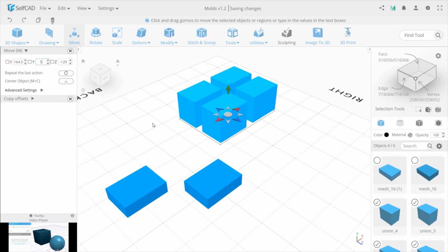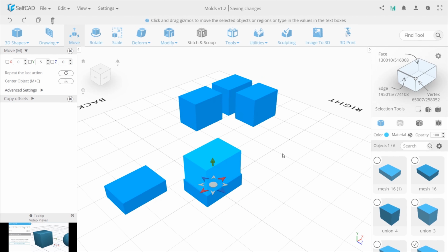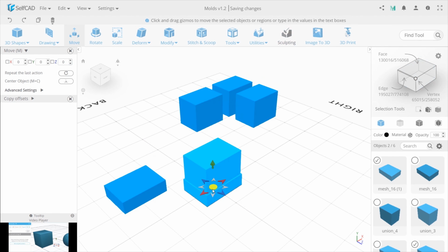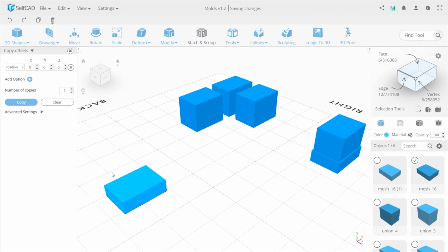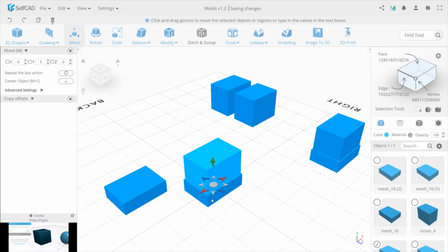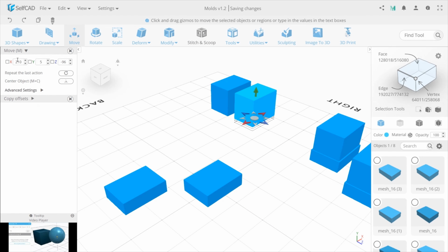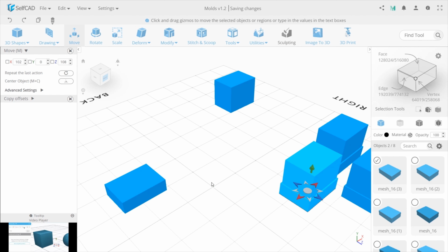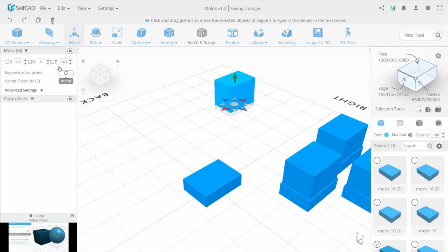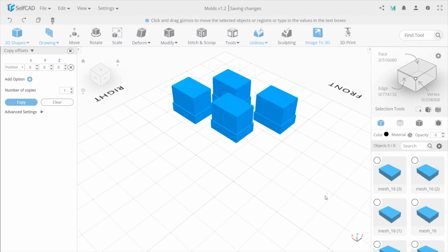Now let's move up the image objects by 5 on the y-axis, so that when we cut out the patterns, we get a pan thickness of 5. Finally, let's align the base with the objects. This time, I'm not using the Align tool, but rather simply centering the objects. For the base, I'm using the center option in the Move tool, and I'm manually positioning the image objects to 0 on its X and Z axes so that we keep the Y axis elevated by 5.